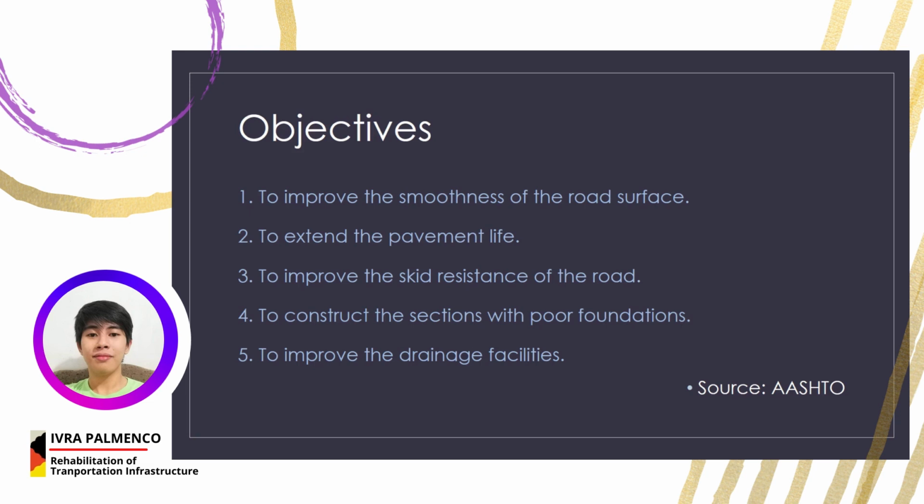And lastly, number five, to improve the drainage facilities. Poor drainage is a traffic safety risk. Water may accumulate on the road like ponds, and accumulated water creates a risk of aquaplaning during rain. A wet surface also reduces friction, which leads to longer braking distances. So, existing drainage networks should be cleaned regularly and extended to receive the maximum flow rate if possible, and proper maintenance of the drains and drainage system can prevent clogging and other unwanted effects.